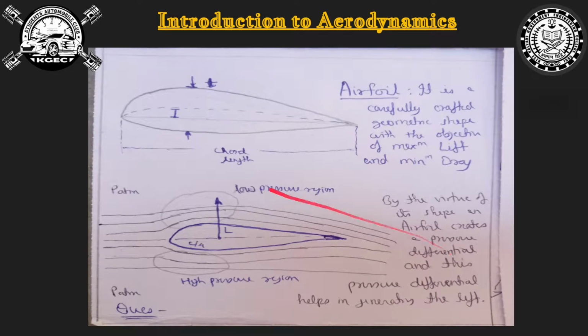So this is a general airfoil design which we saw in the previous slide also. As you see, this is the leading edge, this is the trailing edge, and the straight line connecting these two is called the chord line. And see, this is an unsymmetrical airfoil, right? So chord line does not bisect the section into equal parts. So that we do with an imaginary line.